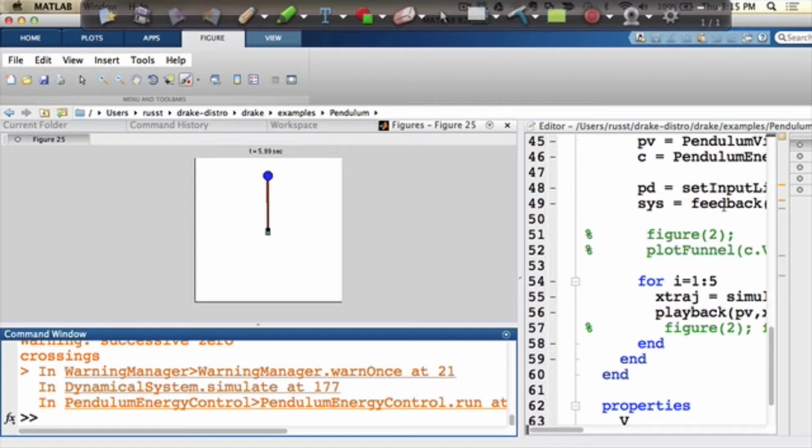How much more efficient is it to switch between the LQR and the energy controller instead of having some proportionality? Like I'm this far away from it, so this controller is input by this much, and this controller is input by this much. So that when you get close, you end up having a bigger scale than that. Right. So you want some soft mixing of the two controllers. Yeah. I think that would work fine as long as you have the property that you're doing only LQR when you get to the top, and you're doing something else away. I mean, the problem is your LQR gains might do really big things. It might actually be hard to mix those in a soft, good way, right?